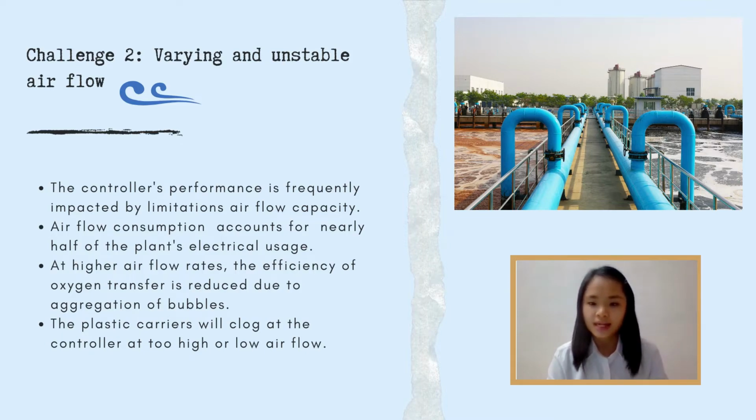At higher airflow rates, the efficiency of oxygen transfer is reduced. This is because of aggregation of bubbles, which reduces the overall transfer area towards the water phase and increases bubble rising times. When the airflow is too high or too low, the plastic carriers will clog at the controller.